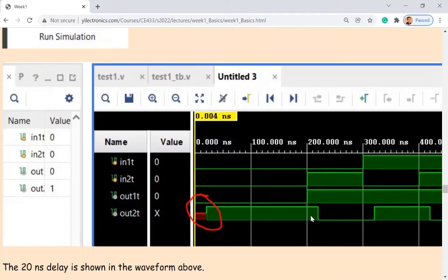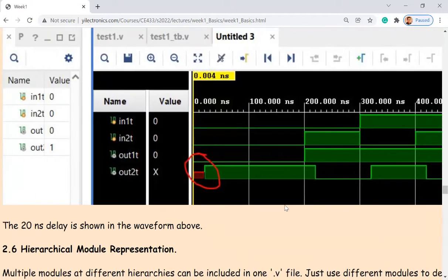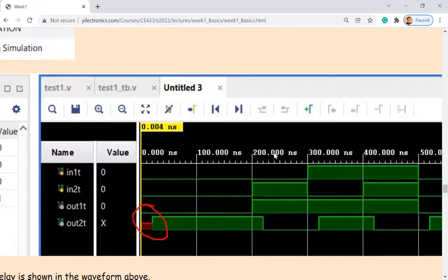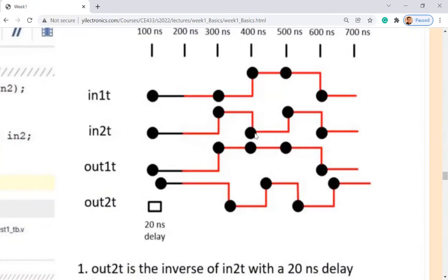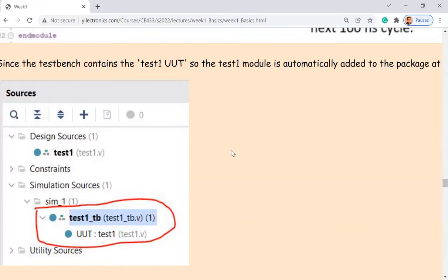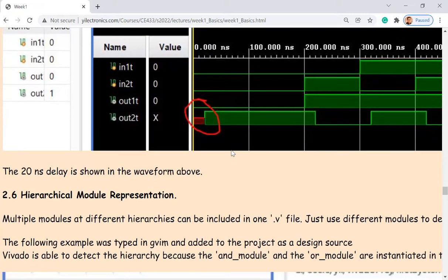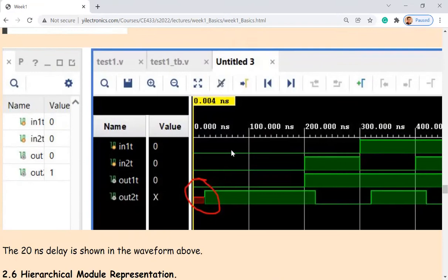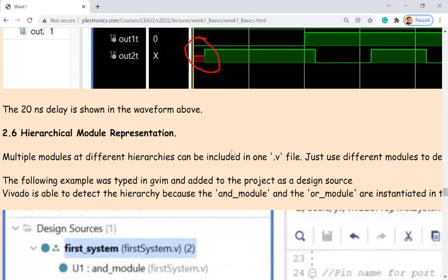That's why if you look at the simulation result, in the very beginning, there's a 20 nanosecond delay, which is red because nothing is being assigned to anywhere. It's called high impedance. It's actually nothing. It's right in the middle. Usually it just shows you it's not high, not low. It's just 2.5 volts if it's a 5 volts logic. And the following curves are exactly the same as what we just analyzed over here. That's how that works. So this teaches you how to use time delays to simulate a circuit and observe the result to verify the logic.